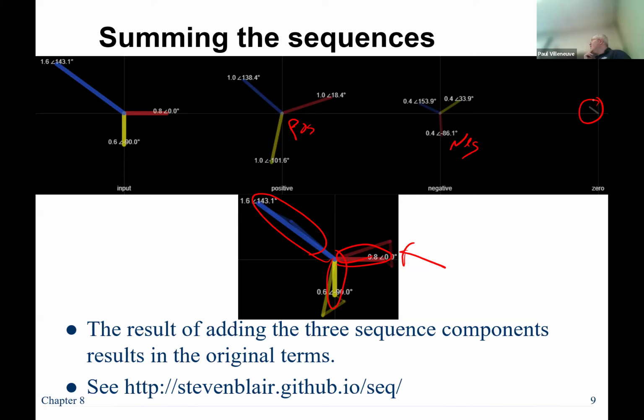And you can see each of the components for each particular phase. Again, in positive sequence, look at the magnitudes. They're all exactly the same, aren't they? Look at the angles, 120 degrees apart. Same thing for negative sequence. Magnitudes are the same. Angles are 120 degrees apart. Zero sequence, I only show the one.